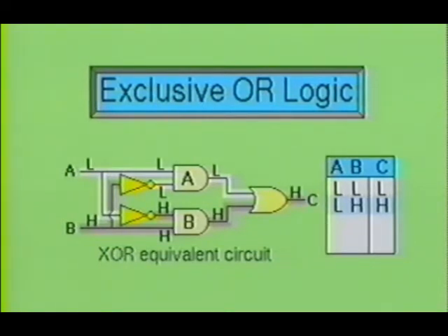The OR gate, being fed by the two AND gates, now has a low from gate A and a high from gate B being fed into its inputs. Remember, if the OR gate has one input or the other, or both of its inputs high, then it will produce a high output. As you notice, this is in accordance with the truth table logic.